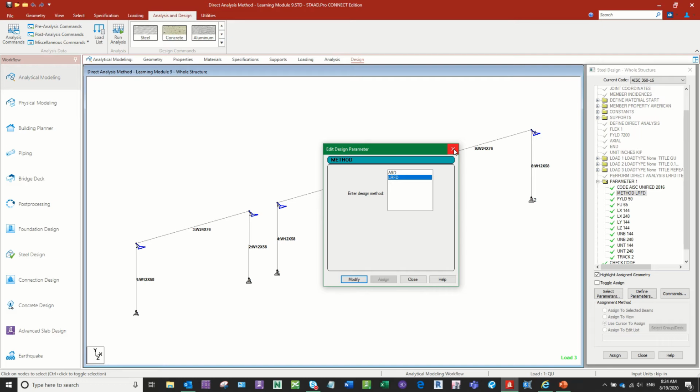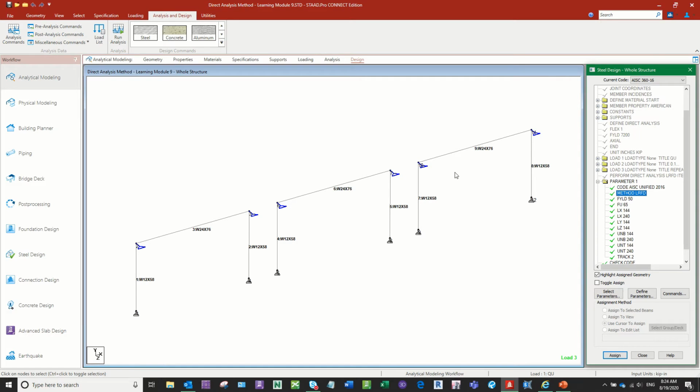Well, that's because it's trying to figure out, when it runs the analysis on the repeat load, should it multiply the loads by 1.6 and divide by 1.6 afterwards. That happens in the analysis. So should it do that or not? That's what's required by ASD.